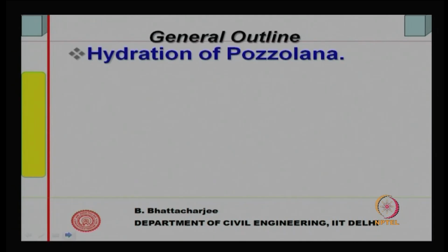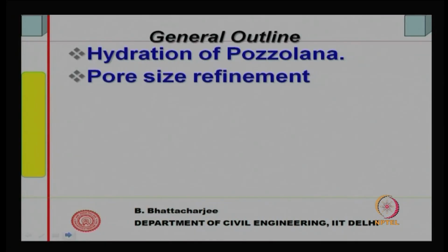Now, in this lecture we shall be looking into how they react, because we define many of them as pozzolana as a class. Of course, you can have non-pozzolanic mineral admixtures as well. We will have a short discussion on those, something like limestone powder. Some of them are inert, but right now we will concentrate on pozzolana. So, how do they react? Hydration of pozzolana we will look into.